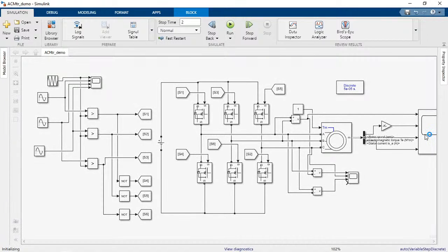Yeah, if you run the simulation, now your motor will get a lesser speed, because we have reduced the magnitude of the voltage. Somehow it can be adjusted, not completely. By changing the frequency only, we can get a various range. Almost small speed has been controlled.